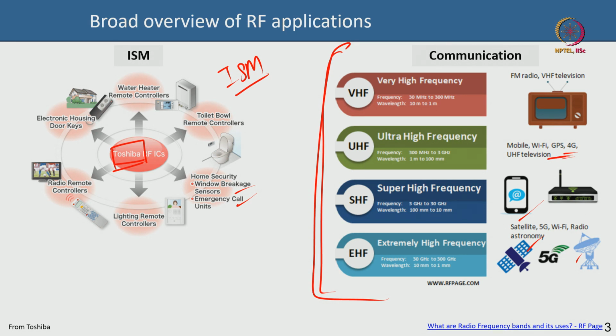You can choose to have your cell phone communication also at that particular frequency as one of these ISM bands, but then it has to be able to withstand that enormous amount of interference that will come. Imagine a microwave oven, it's in every house, and the microwave oven will interfere. So you have to be immune to that. That's why people do not try to operate on this, but it's very low cost. All the other components and accessories available there are very low cost, okay.